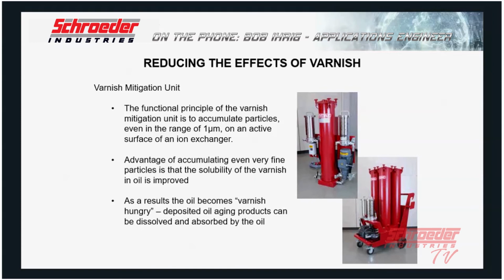These are very effective since it's a chemical filtration process. It's also permanent, and it can even solve, or I guess attract, dissolved varnish in the fluid. So it doesn't matter what temperature the fluid is at per se. In most circumstances, if it's really hot fluid, there might be some issues, but generally speaking, you don't have to have the varnish agglomerate or be cool to take care of the situation.